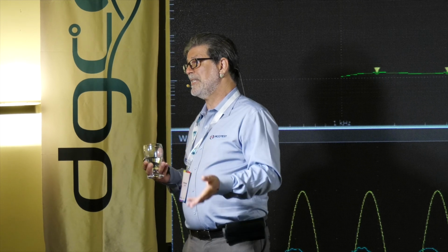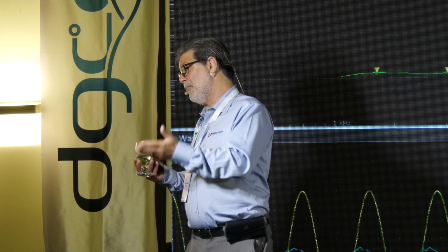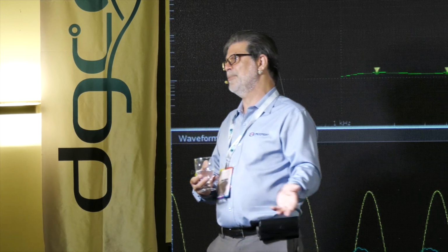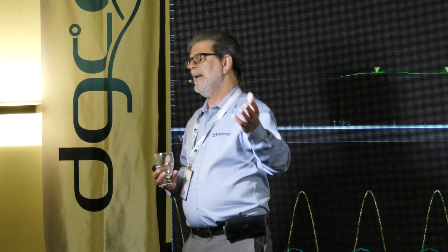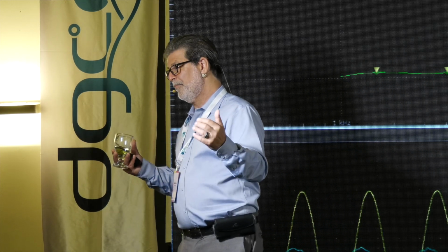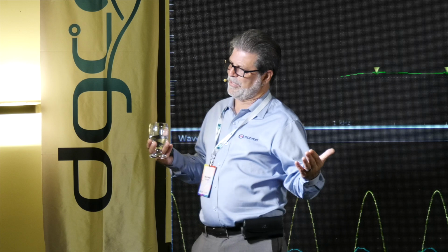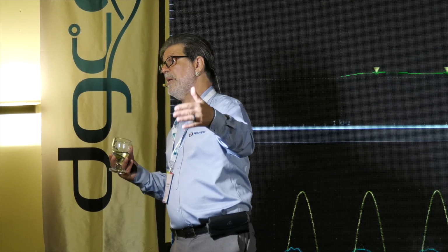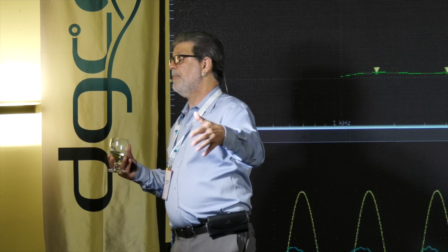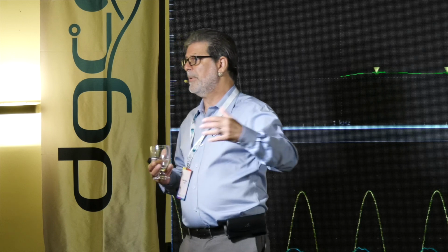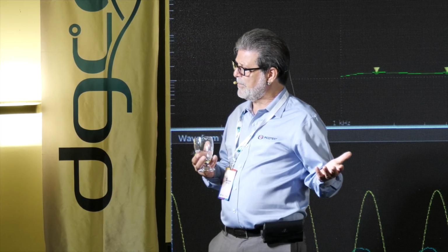So I could control excess inductance by choosing the output filter inductor. And in order to tolerate lower filter inductors, I needed to push the switching frequency up. And I did this balancing, threading a needle, trying to get to where I could tolerate the switching losses and end up with a total noise budget that ended up meeting their chip requirement. And the budget was very different. I ended up with a lot more noise from ripple, but a lot less noise from dynamic currents.